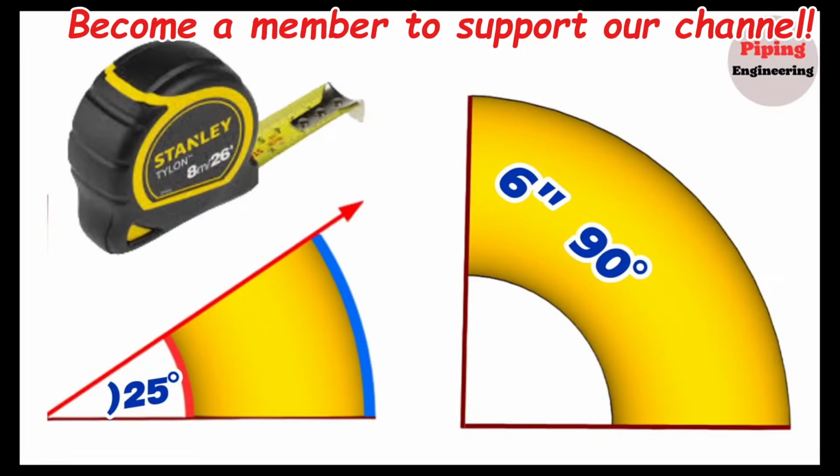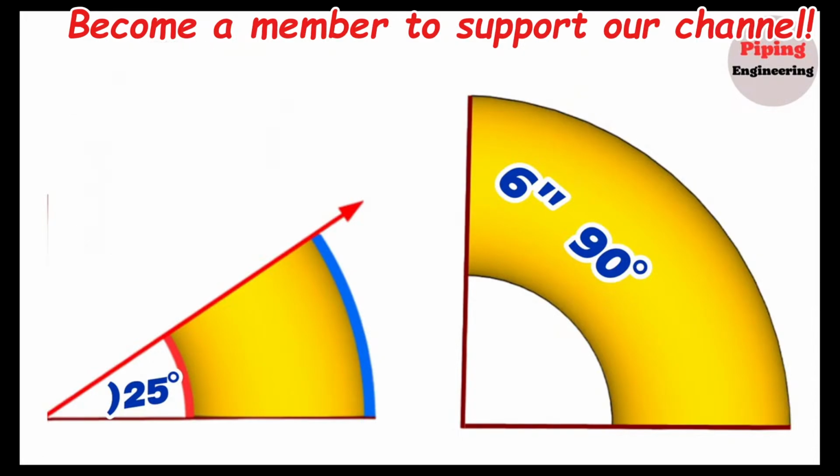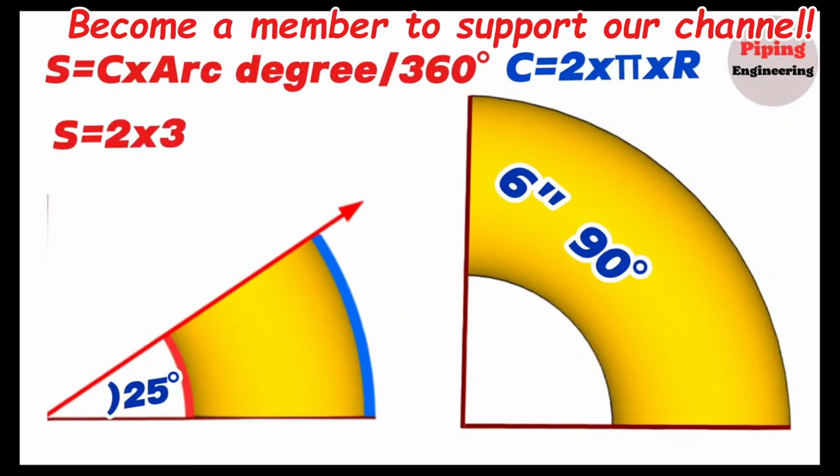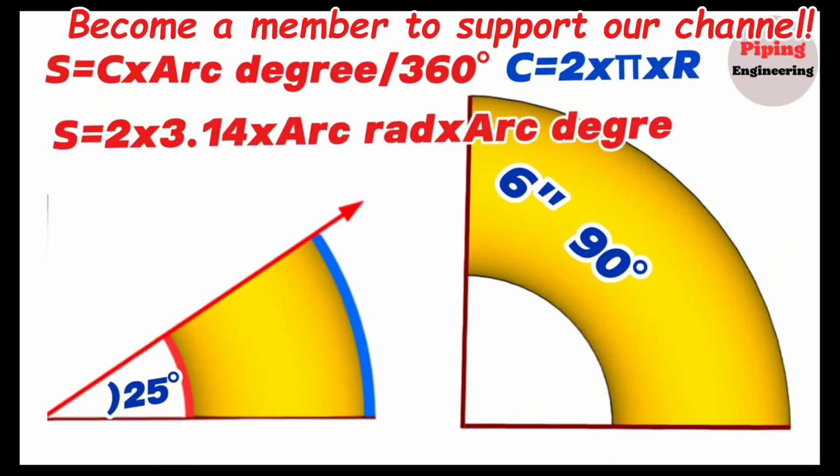Before learning the formula for cutting an elbow by any degree, let's learn the arc length formula. We know that the formula for the arc length S is equal to the circumference of the circle C multiplied by arc degree A divided by 360 degrees. Also, we know that the formula for the circumference C is equal to 2 multiplied by pi multiplied by the outside radius R. So, the arc length formula will be S equals 2 multiplied by pi 3.14 multiplied by arc radius multiplied by arc degree divided by 360 degrees.